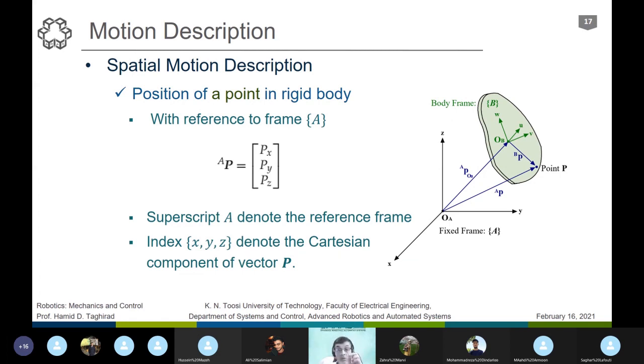The robot works with a point, which is usually the end point of the end effector. We call this point P, and we can represent it very simply. Again, we can have a P with a 3-coordinate system. We can have this represented in the fixed frame, which gives us an absolute position of this point. We call its components Px, Py, Pz.